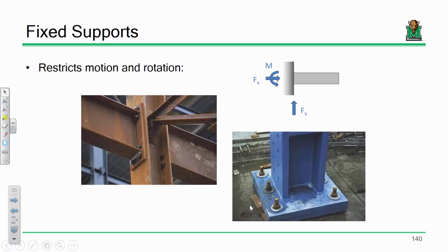You can imagine the construction foreman was sweating bullets that day, with this multi-million-dollar project, and they get to the middle and it's too long. So you want to know how they fixed the issue? Well, it was 95 degrees that day. So how do you get that girder element shorter when it's 95 degrees? You dunk it in the river. So they dunked it in the river and cooled it down and it contracted. They put it in. I was like, now that's engineering.